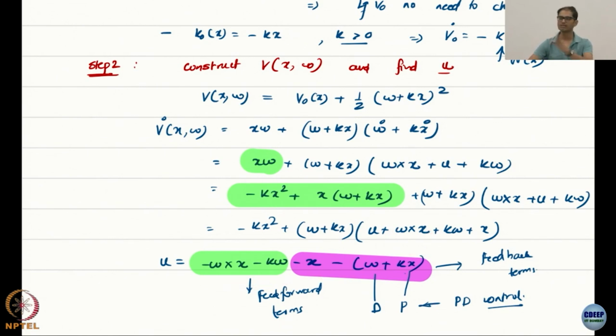Even in the Syscon department, when you do some experiments with 2DOF and this and that, the typical controller that you are experimenting with is always a feed forward or a PD plus I controller. And you know that the purpose of the integral is to, in the linear case, sort of do the job of the feed forward terms. Okay, so we discussed this.